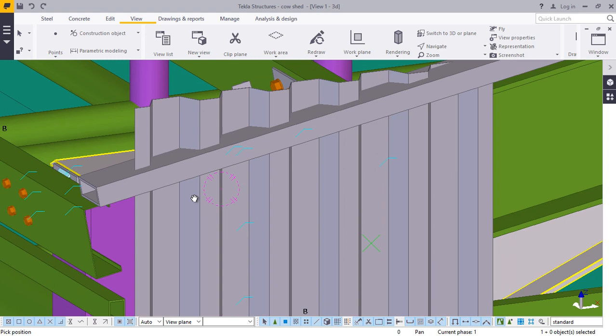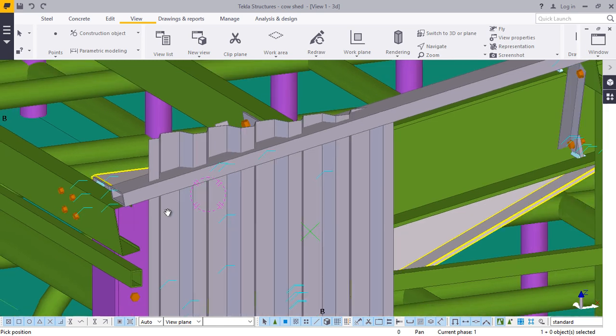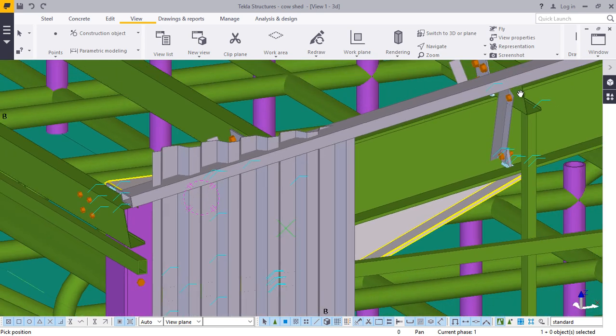We want to trim off this extension, and that is the main reason why I was telling you that prior to placing your sheet, make sure you place this steel profile that will be able to guide you in trimming off the iron sheet extensions, to enhance the profile following of the rafter.